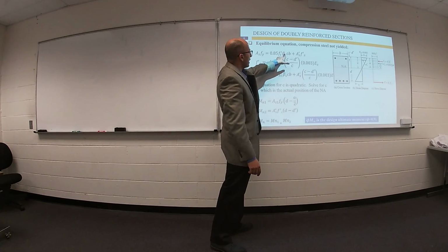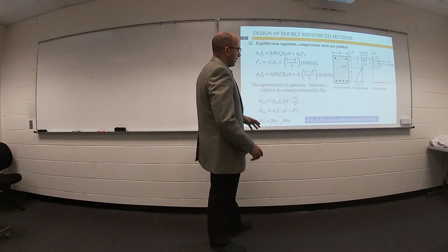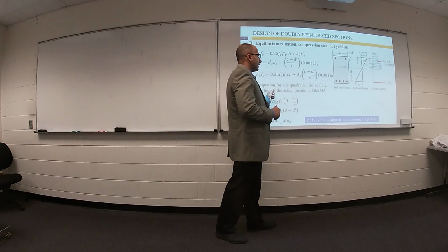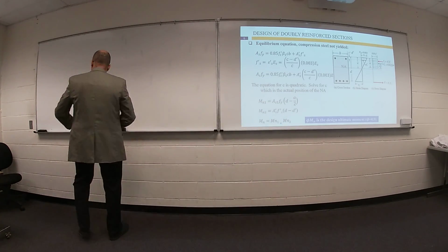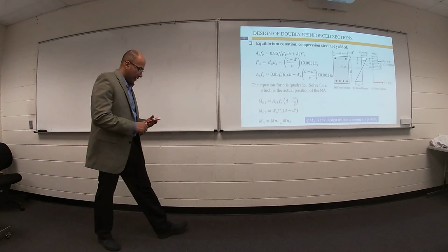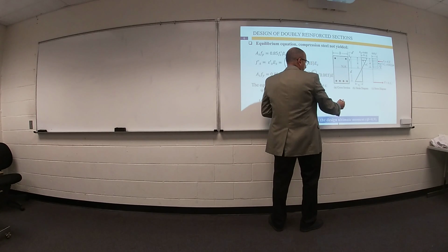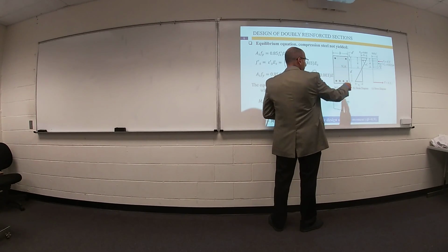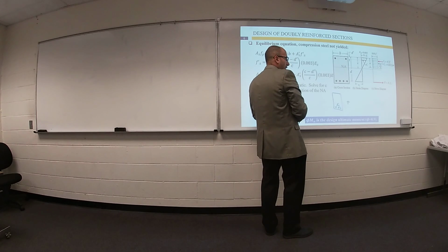After you remove a and put it as beta 1 C, you will get an equation of second order, a quadratic equation. You solve for C and then you can get your moment by assuming your cross section equals: first part, your concrete with area steel 1.